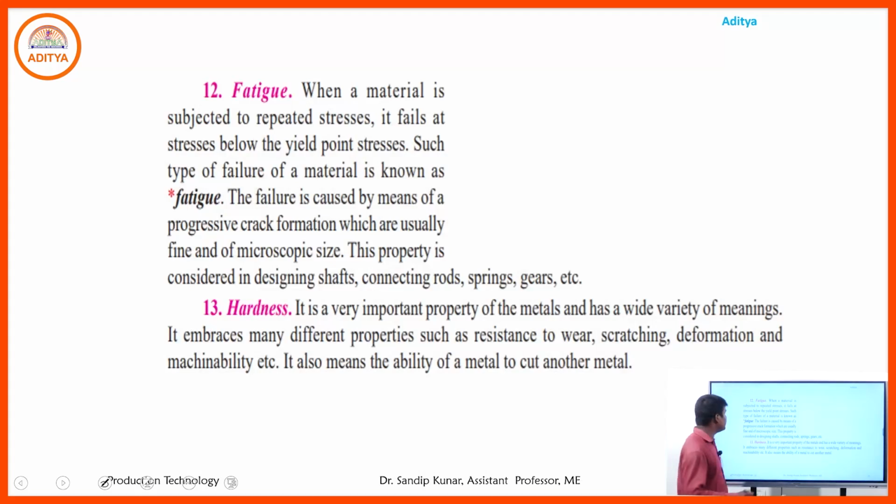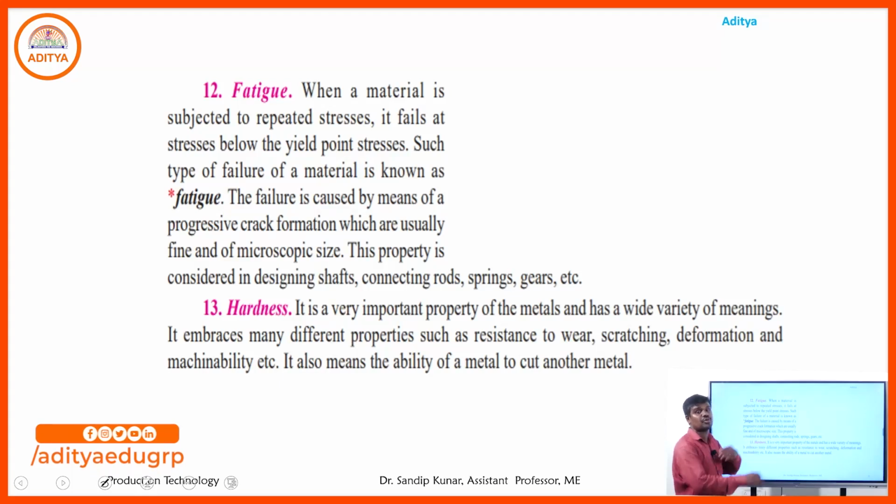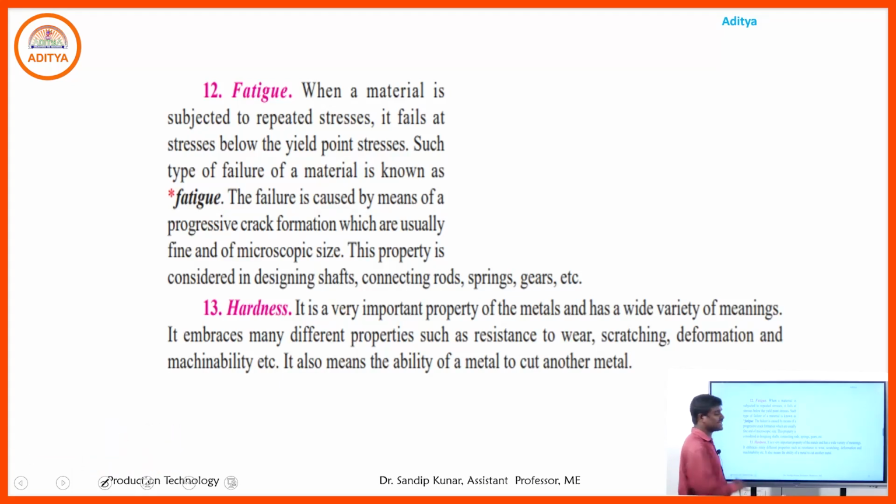Fatigue. What is fatigue? In this case, we apply repeated stress, meaning repeated loads, to the material, and due to the application of repeated loads and repeated stress, it fails at stresses below the yield point stress. It will fail permanently below the yield point stress.